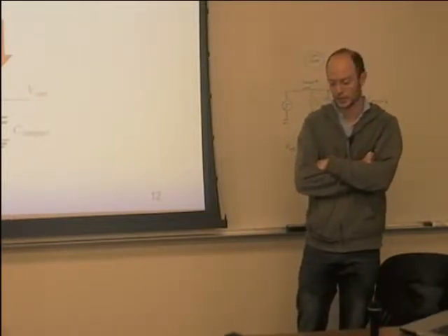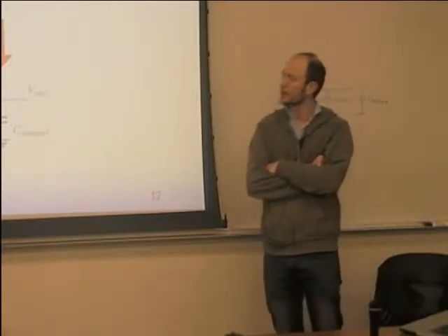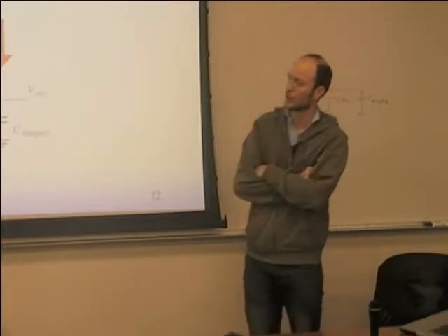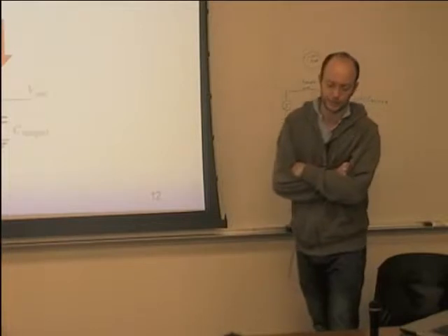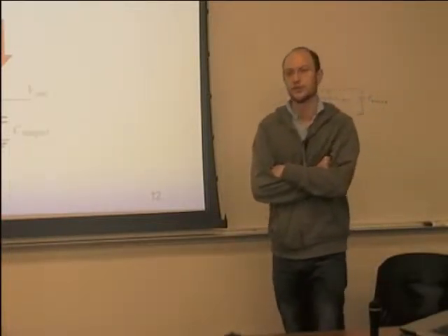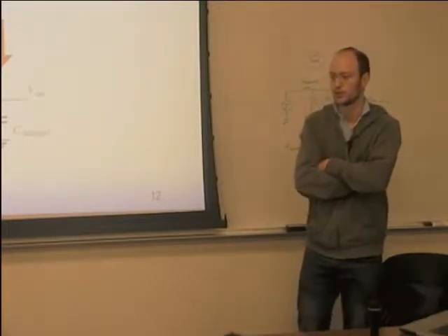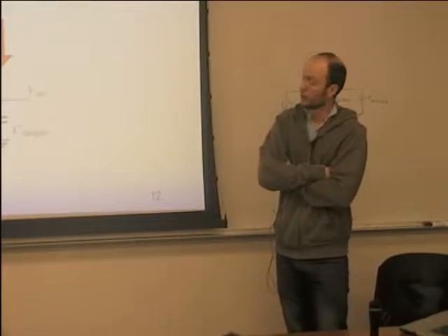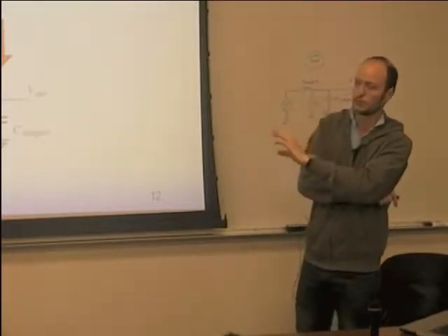If you take a transistor and, for example, tie the gate to VDD and tie the drain to VDD, and the source is at ground, and this is an NMOS, or you do the opposite with a PMOS, then this would be the resistance of the driver when it's pulling down. Or actually, to make it more similar to a resistor, you can think that the drain is low enough that it's in triode.